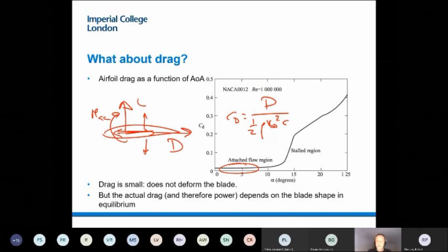But that gives us a huge advantage in terms of aeroelasticity because drag is by far the hardest thing to compute, but it's the one that in terms of aeroelastic performance has the least effect. So we can get away with simpler methods for aerodynamic design when we're concerned about how wings are deforming, how blades are getting loaded in unsteady conditions.